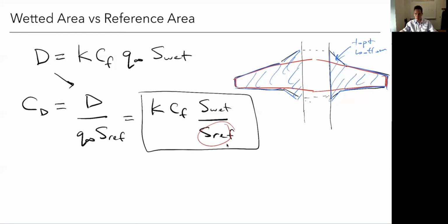The trapezoid is really just this 2D projected area. It doesn't have a top and bottom. But this wetted area, this is this entire surface again, right? We dip this in ink and we're trying to see what parts are colored by that ink. And here approximately it would be this flat shape times 2, right? Because I've got the top and bottom surface that the fluid is moving around. In the book, there's also a correction for thickness, right? Because this is thick and has this three-dimensional shape. And at this stage, we don't actually know the exact shape. We can approximately get it from thickness.